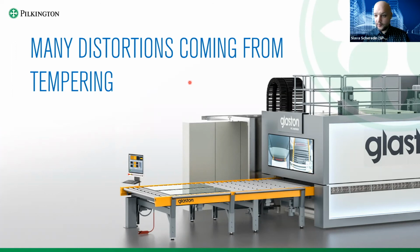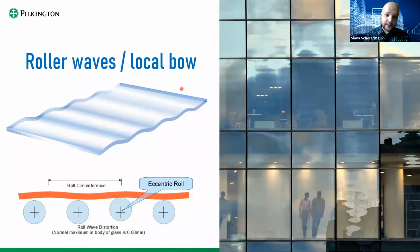But today we'll be talking about it shortly, because from tempering, the first thing you see on many buildings is roller wave. This happens because in the tempering furnace, glass is heated to a temperature beyond its softening point, and when it gets cooled down, it remains with these bendings, the roller waves. The general rules about roller waves, there are two.